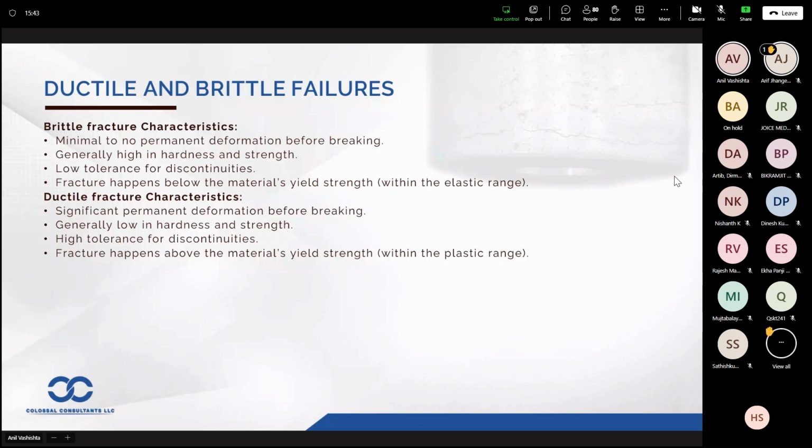Other corrosion categories which you would have heard of are subsets of these corrosion phenomena. In addition, there are corrosion mechanisms, which I just mentioned. MIC is where the pitting corrosion happens. We have pitting corrosion, and stress corrosion cracking is a subset of environmental induced cracking.